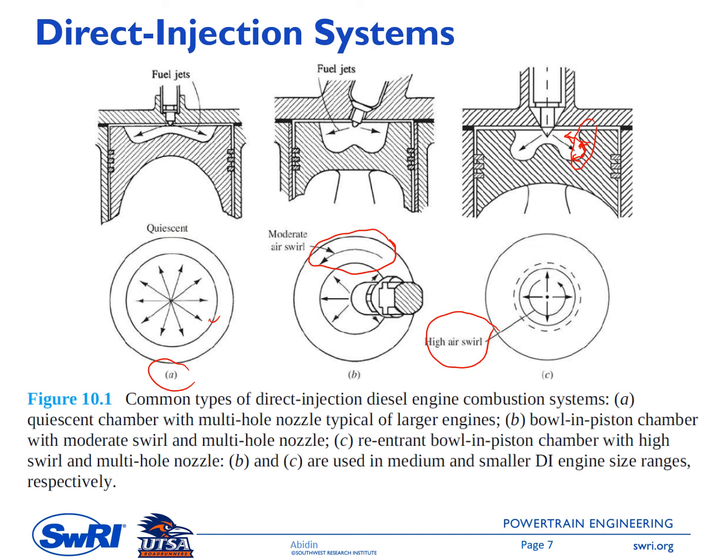If you remember, the wall heat transfer here is Q equals H times A times delta T. So assuming similar H and similar delta T between system A and C, system C has a higher A, which results in higher wall heat loss through the piston surface.